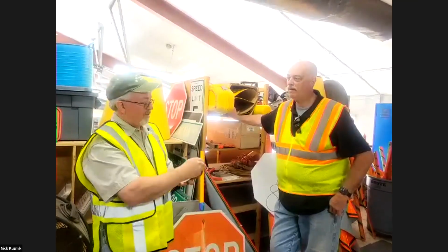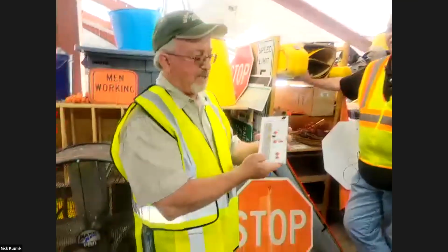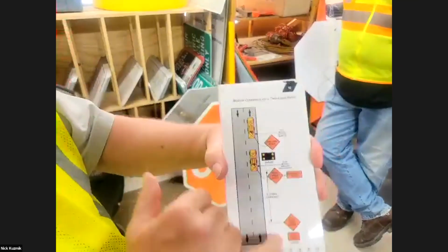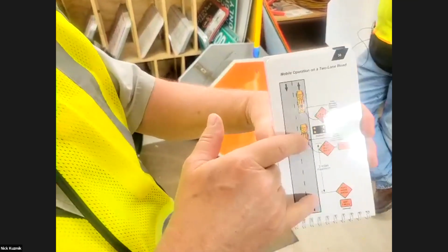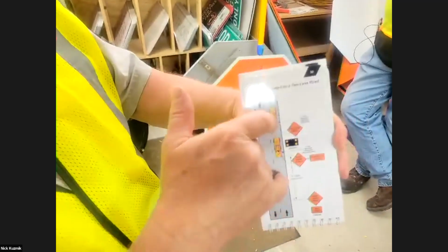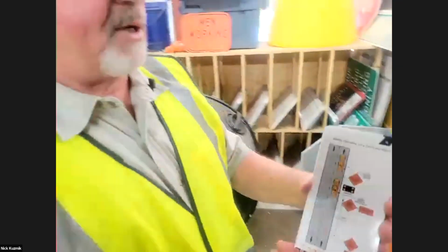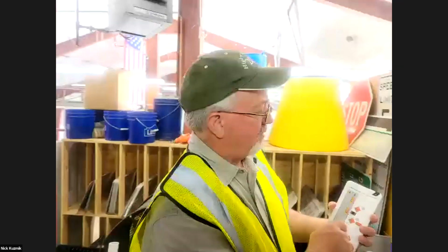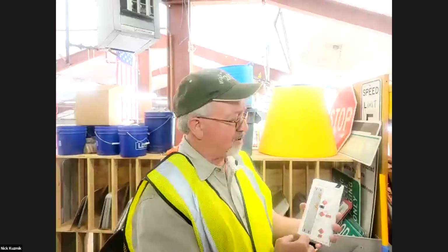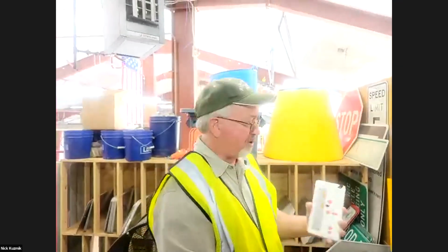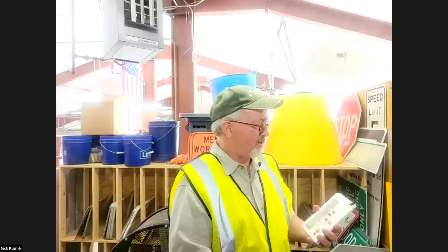It is actually. Again, in our flagger's handbook, it has a layout of how the flag should be. Again, they've got your advance warning to let you know that there are, and then it says 5 miles is a maximum. But again, you should have something on the trucks. If it's a mobile operation, the minimum height off of the ground is going to be 1 foot. So again, you want a 1-lane road, you want these buffer trucks to try to work with you to protect the workers. But you can do a mobile operation, but you still should have some sort of advance warning for the traffic to know what's going on.